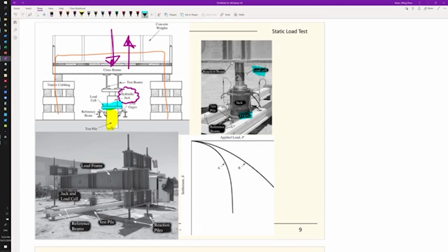Reading the dial gauge would be the old school way, or we can install sensors. Nowadays, both the load cell and the displacement reading are by the LVDT. LVDT stands for linear variable differential transducer, which is set up to pick up the displacements. Now you get those electrical units, displacements and load in voltage, and then you can convert that with calibration factors back to engineering units. So you get the pounds and centimeters readings.